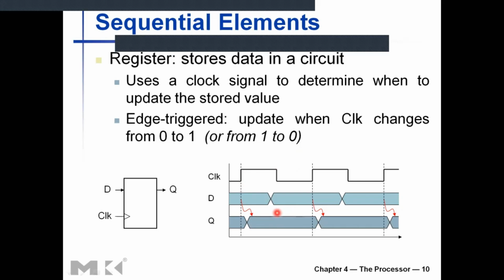I hope there's nothing much to discuss there. You're familiar with these concepts. The only thing to discuss is that the operation in a sequential element happens at the edge. When we use flip-flops in a register, you take the incoming data and latch it, or update the state based on the incoming data at that edge in the clock.